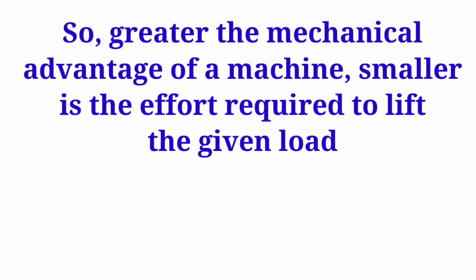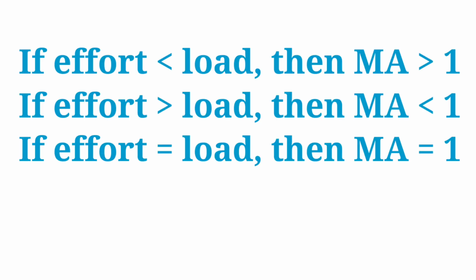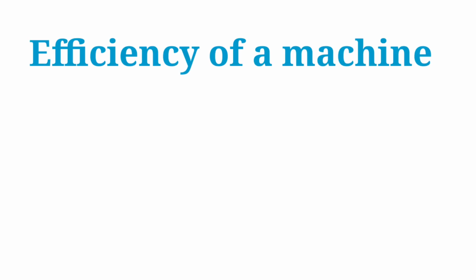Greater the mechanical advantage of a machine, smaller is the effort required to lift the given load. If effort is less than load, then mechanical advantage is more than 1. If effort is more than load, then mechanical advantage is less than 1. If effort equals load, then mechanical advantage equals 1.